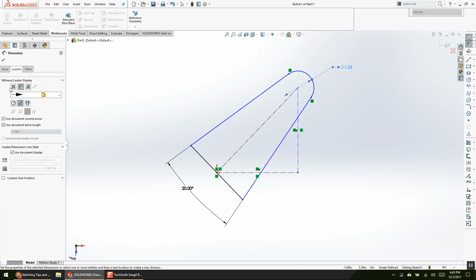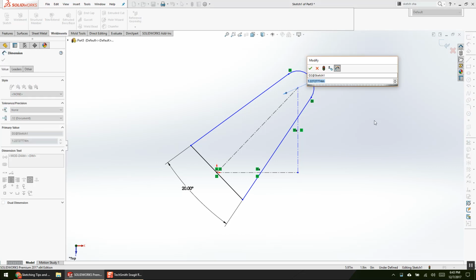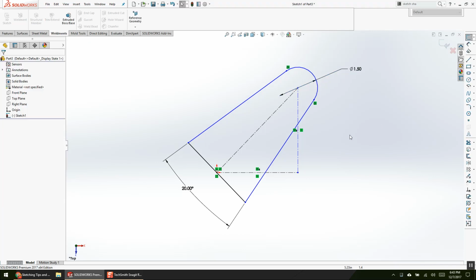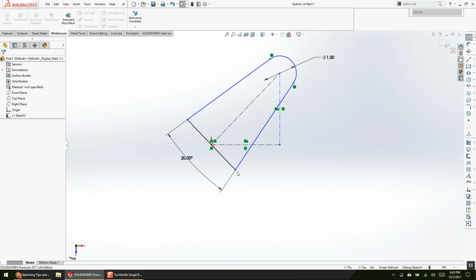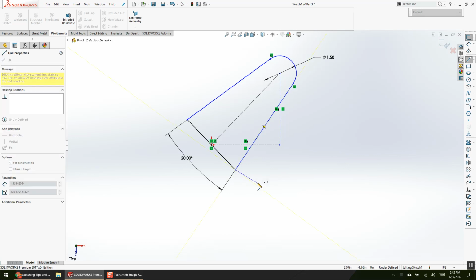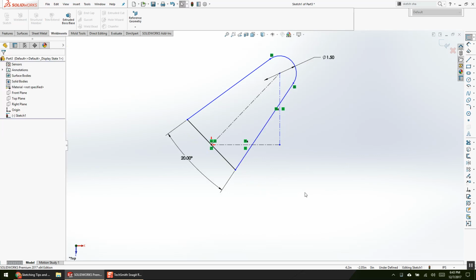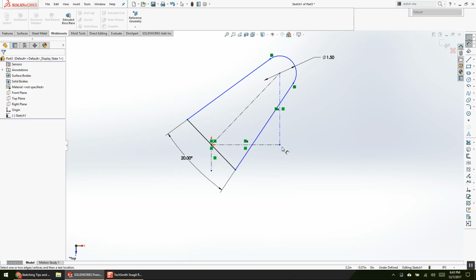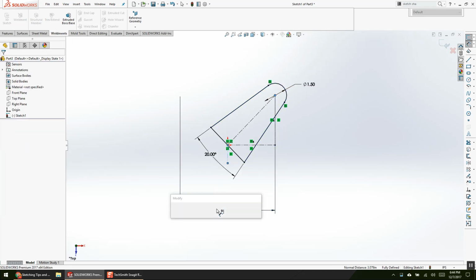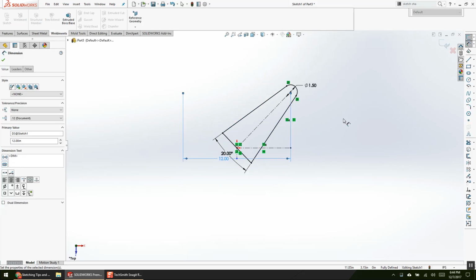I want this to be a diameter value. So we'll say that is 1.5 inches for funsies. And what was it, 12 inches? I don't remember. We'll figure it out. So here, I'm going to pick on the center of this and my construction line and type in 12. Now I'm a guaranteed 12-inch bolt hole pattern off my one leg, and I'll pattern this.